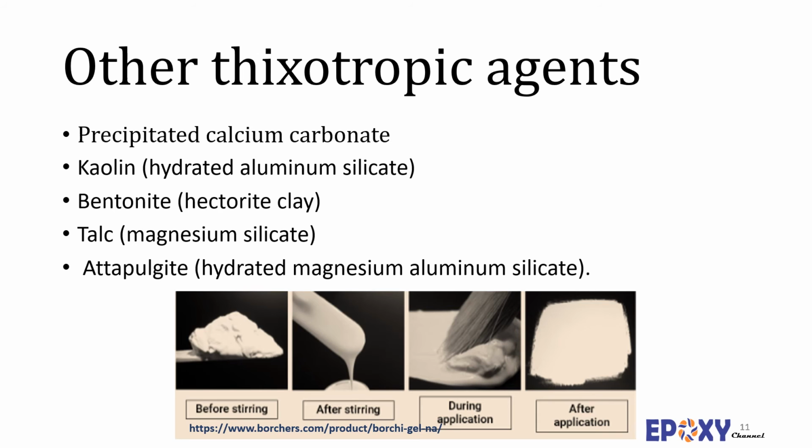Coarse particle sizes of 10 to 75 micrometers are commonly used at loading levels of 5 to 13%, whereas fine talcs of 1 to 10 micrometers are more expensive and require intensive dispersion processes. Platy grades also enhance barrier properties and air, water, and chemical resistance.